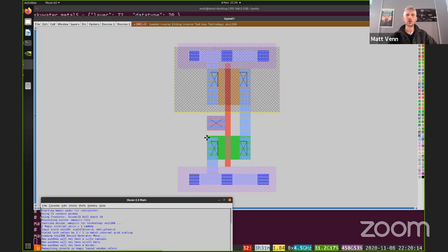Whenever in engineering, we're always making compromises. Here, what we want is a perfect inverter, but we've seen that when they switch state, they waste a tiny bit of energy. And part of that is because we have a tiny bit of capacitance, this gate capacitance. So every time you change it, you have to charge up or discharge this gate.